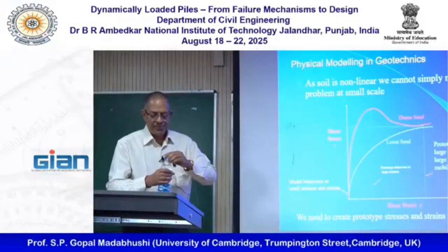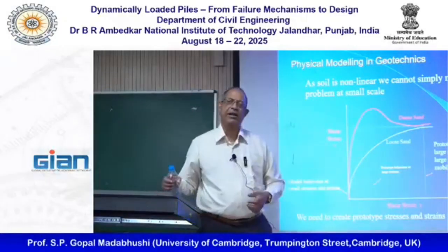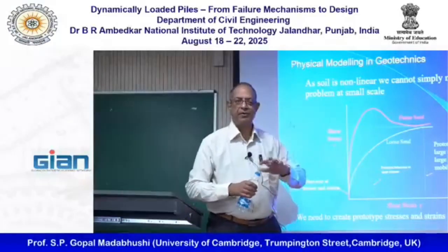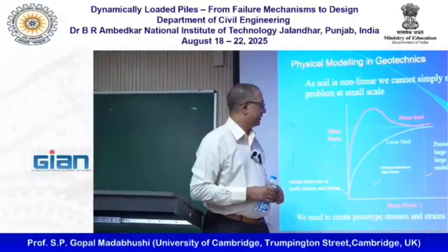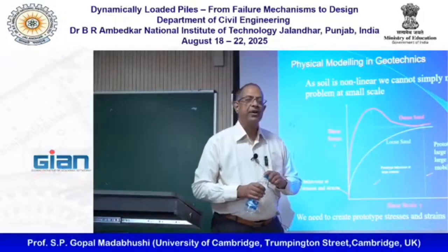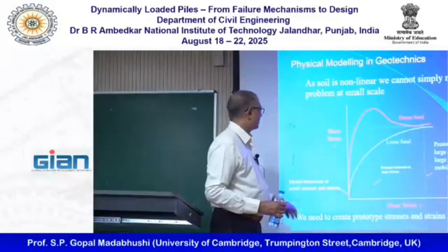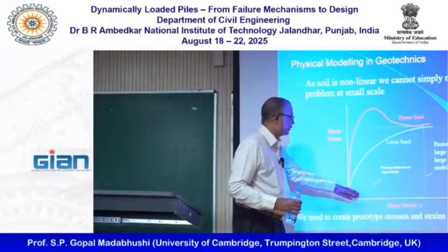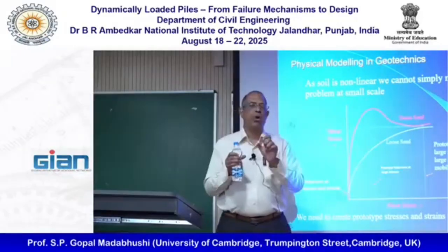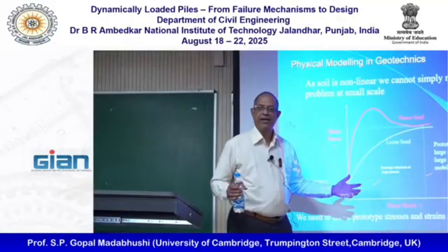Anyhow, so that works for hydraulics. People do something similar in structures as well. You can scale down models and build them and test them in wind tunnels if you want to look at the vibrations of bridges. In soil mechanics, we have a problem because if you scale everything down, our stress and strain are going to be small, and the model stiffness is very high. It's almost vertical, so the stiffness is very high.